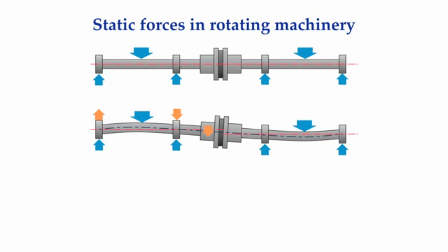The shaft on the left produces forces on the shaft on the right also. Through the coupling, the shaft on the left induces an upward force on the shaft on the right. This force now produces an additional force on the inboard bearing in the upward direction, but it will produce a downward force at the outboard bearing.